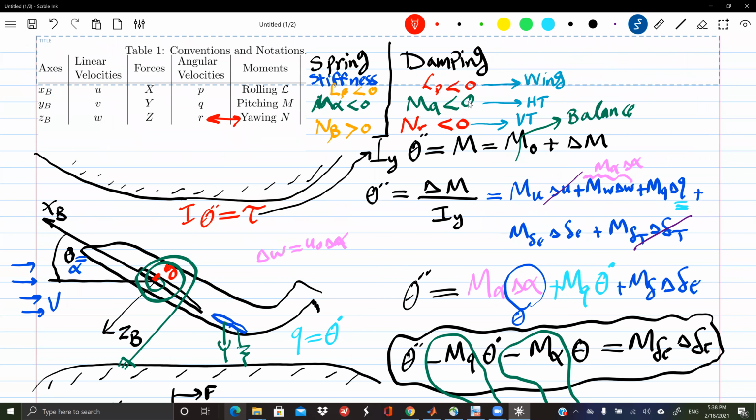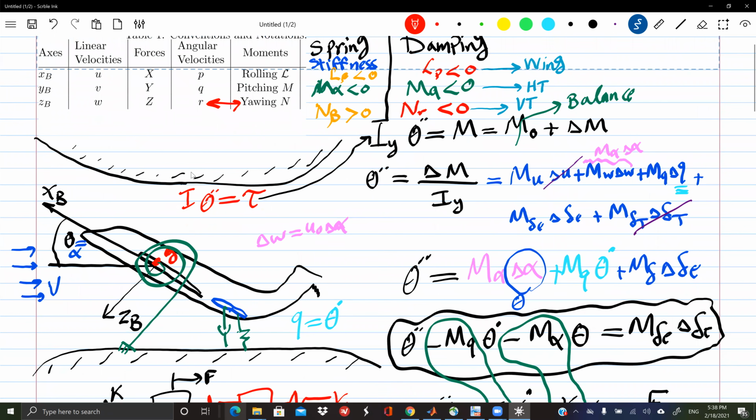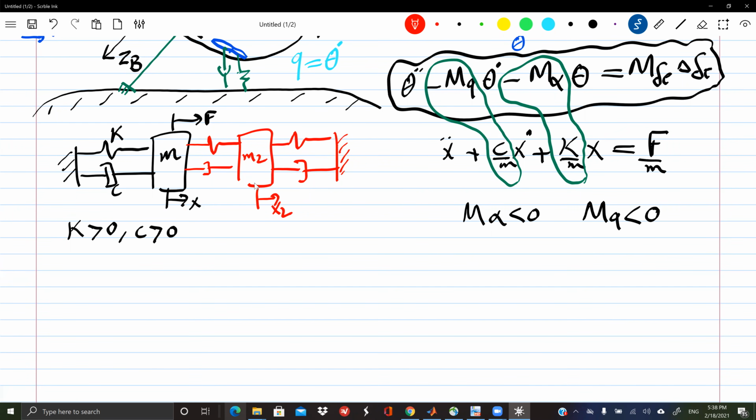This was in the first half, and this was last lecture. So we have stiffness and damping in all directions separately, but they may interact with each other. They affect each other, so that the result may be unstable. I can give you here indeed a combination of K's and C's, stiffnesses and damping, such that this system is unstable. If you touch it, it blows up.